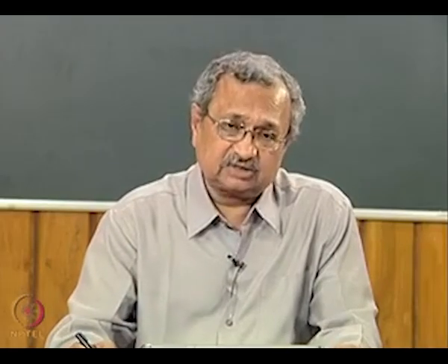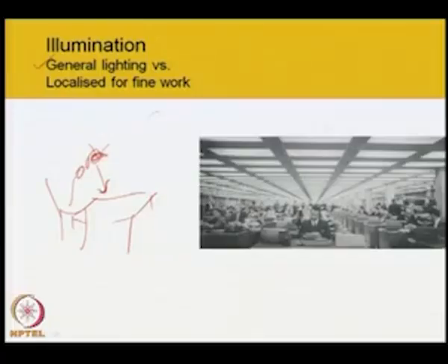Normally, what happens? An incandescent lamp provides shadow. Now, whether the shadow is necessary to complete the task or not. Like when we see a meter reading, the needle and its shadow should match together to give a proper reading. In such cases, the shadow is necessary, but when we require even lighting that is still localized, the diffused lamp system should be better.